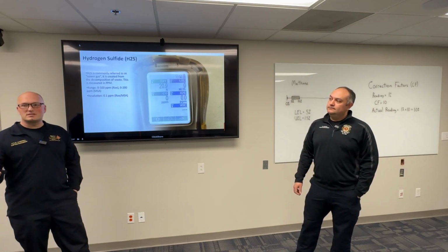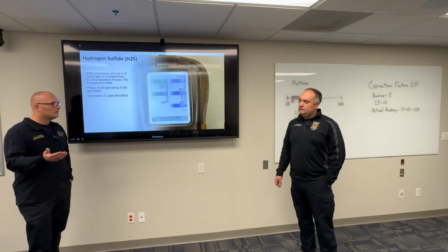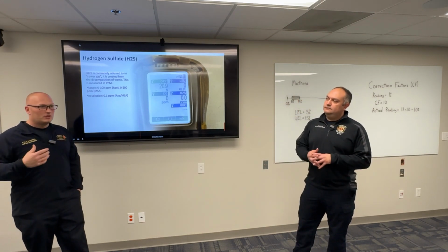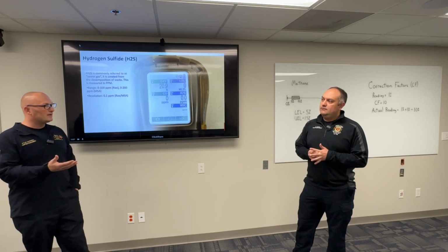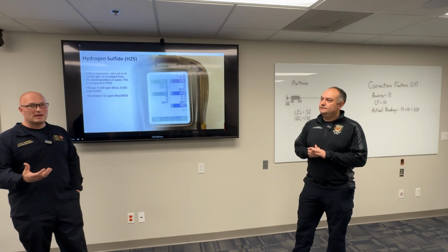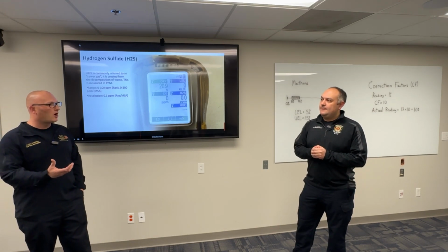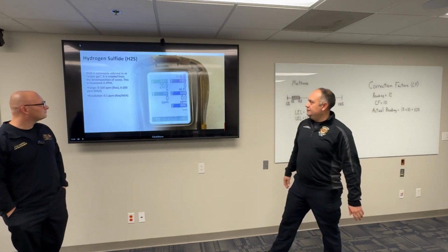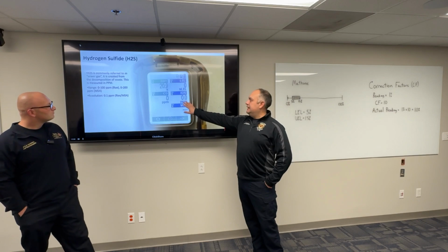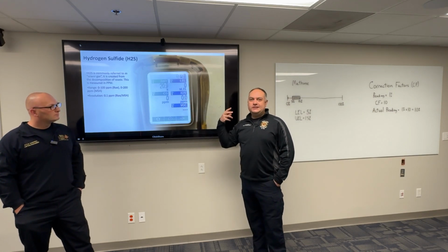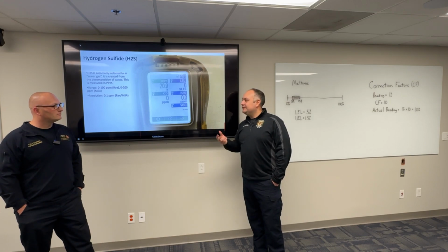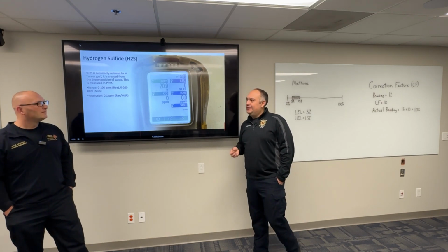And then also with this is olfactory fatigue. We were talking about that, that's whenever you're not smelling it anymore. That can be pretty dangerous, and your meters will always show you what you have going on, even though you're not sensing it anymore. Exactly. So if you had a reading of 95 parts per million, but all of a sudden you stop smelling the H2S, your body's telling you, oh, I think we're fine now because I can't smell it anymore. That's not true.